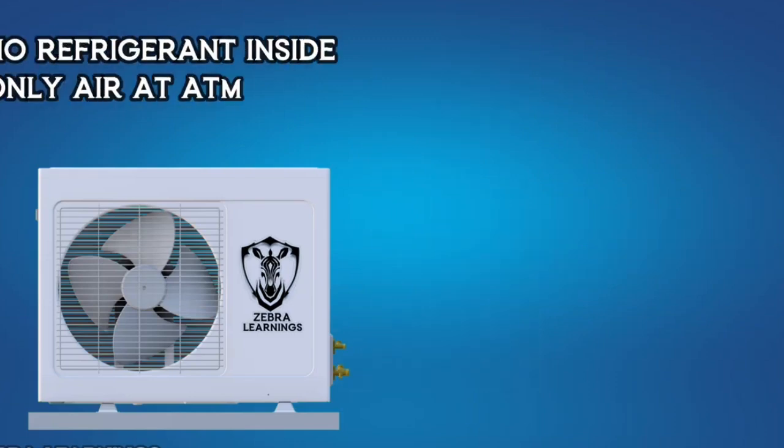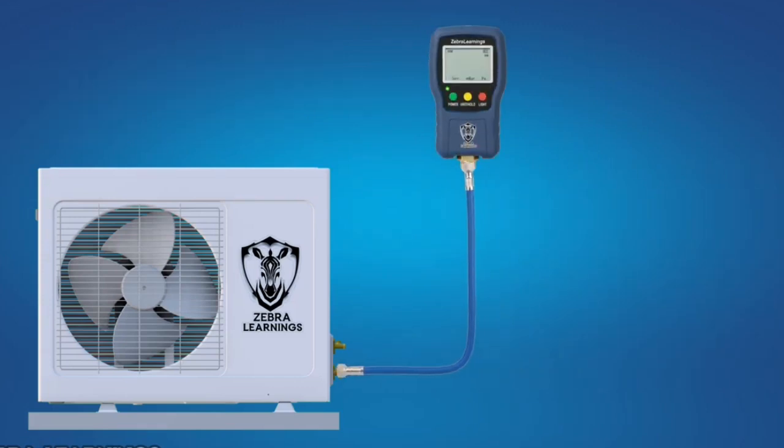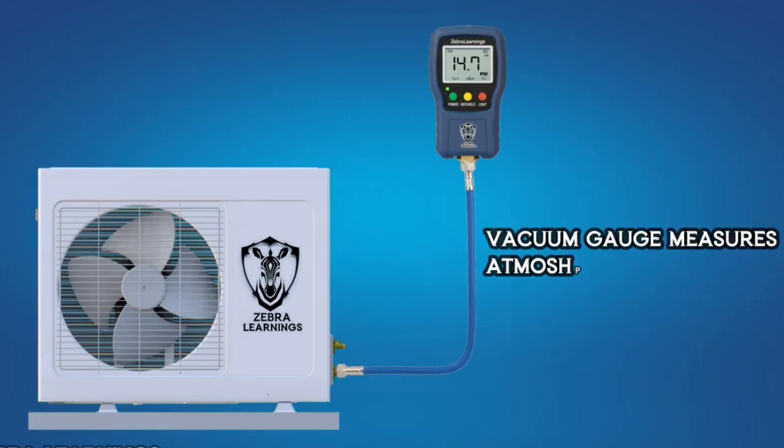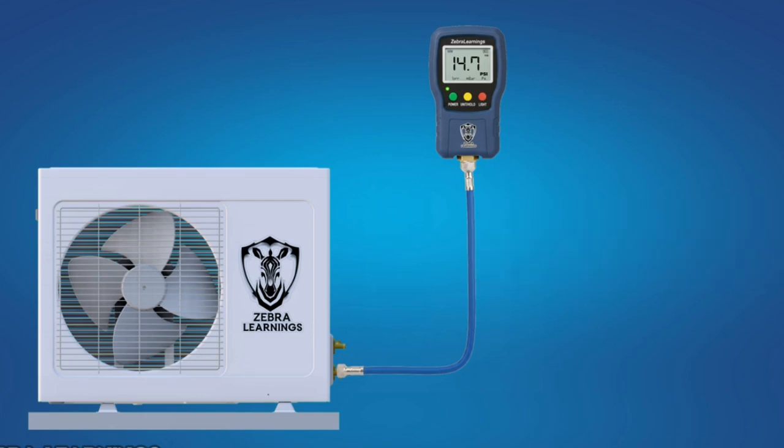Now, let's take the same outdoor unit again. There's no refrigerant inside it. When we check the pressure using a vacuum gauge or Micron gauge, it shows 14.7 psi because a vacuum gauge measures absolute pressure. When we perform vacuuming, we are actually reducing the pressure inside the unit below atmospheric pressure. That means we are pulling the air out of the system until the pressure becomes much lower than 14.7 psi.